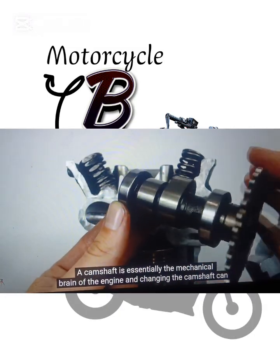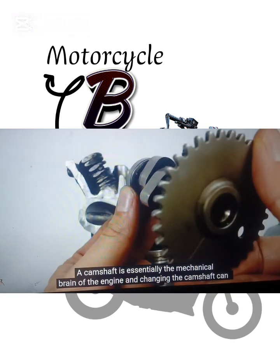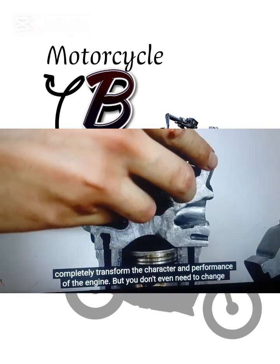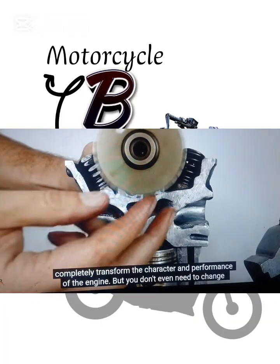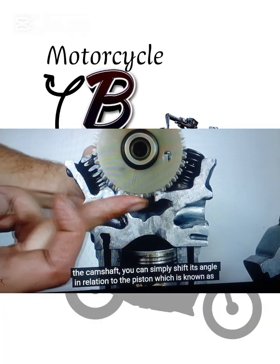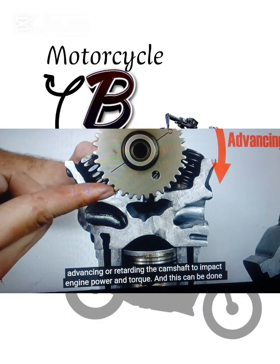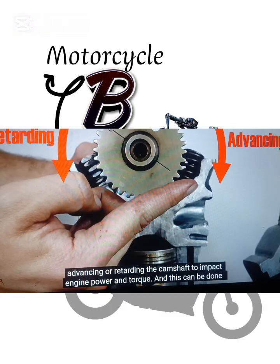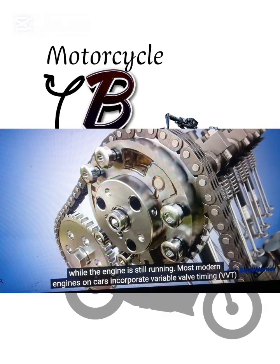A camshaft is essentially the mechanical brain of the engine, and changing the camshaft can completely transform the character and performance of the engine. But you don't even need to change the camshaft. You can simply shift its angle in relation to the piston, which is known as advancing or retarding the camshaft to impact engine power and torque. And this can be done while the engine is still running.